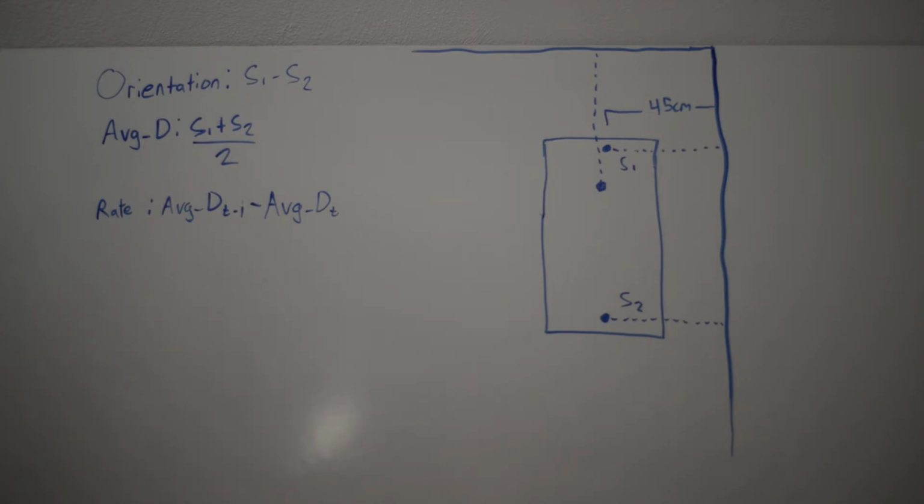These three data points are weighed by certain factors and added together to set the speeds of the left and right motors such that 1. The rover stays relatively straight, 2. It maintains a reasonable distance from the wall, and 3. Counteracts oscillation and does not overcorrect. You can see the resulting wall following in the following video.